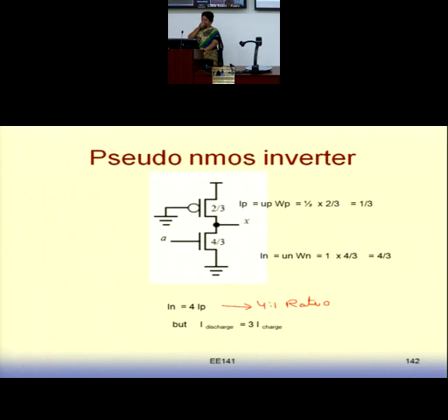Here it is 3:1. But transistors are designed in the ratio of 4:1. That is to be made clear in your mind. Anybody, Goa campus also, you can design a particular combination which can lead to a pull down current 4 times the pull up current.